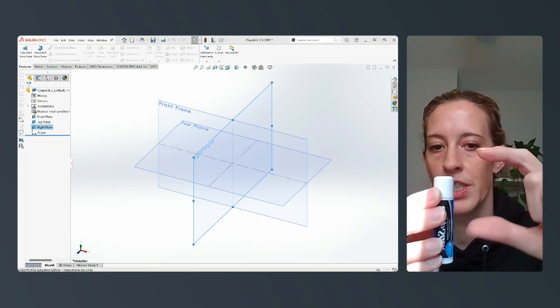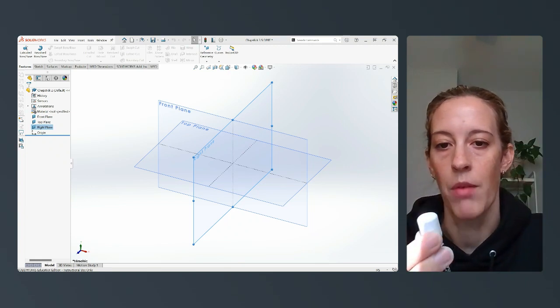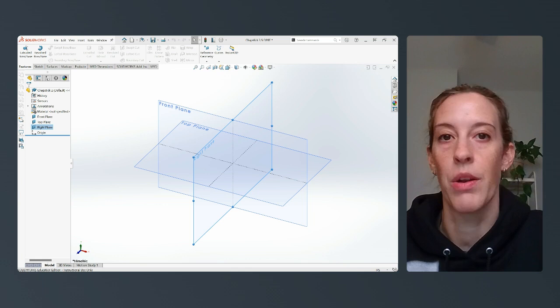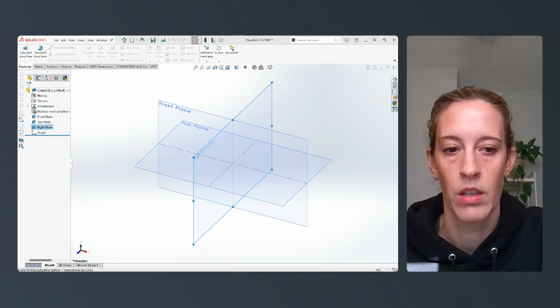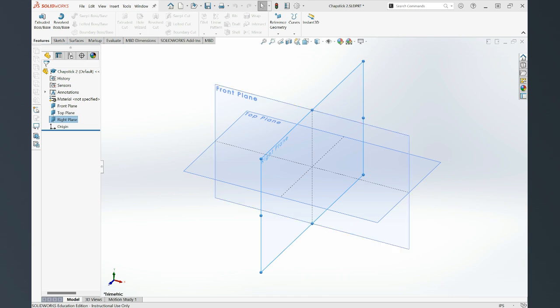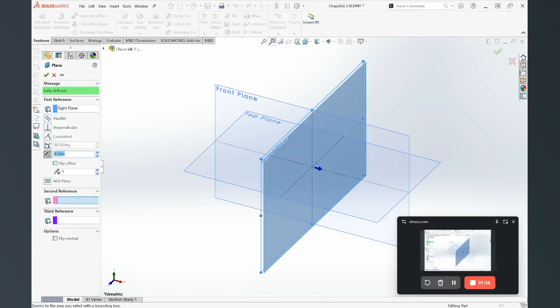And these planes will just kind of help me guide the model and help me avoid remeasuring things or trying to remember dimensions that I've already used earlier. So the first plane will be the scroll wheel height plane. And remember, I can click here on reference geometry and plane.